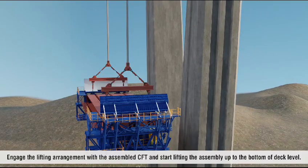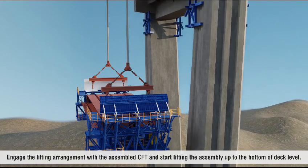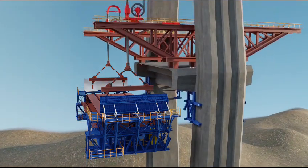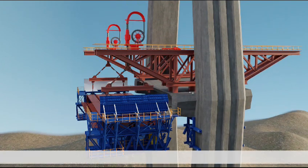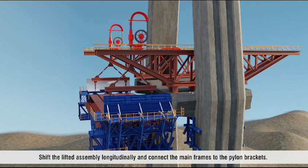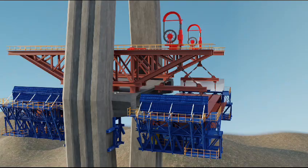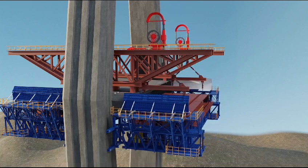Engage the lifting arrangement with the assembled CFT and start lifting the assembly up to the bottom of deck level. Shift the lifted assembly longitudinally and connect the main frames to the pylon brackets. Similar operation is done on the other side of pylon.